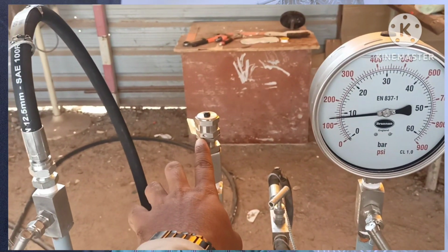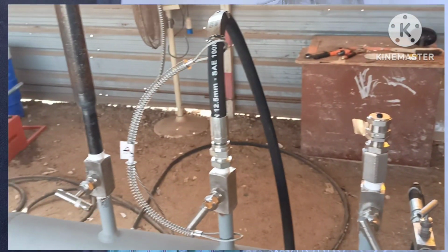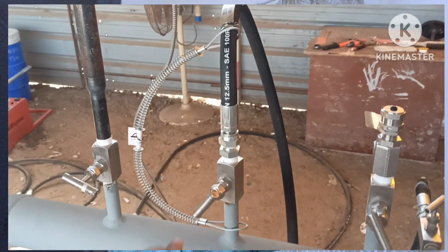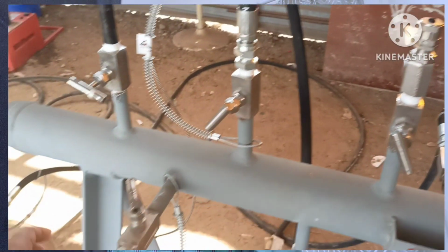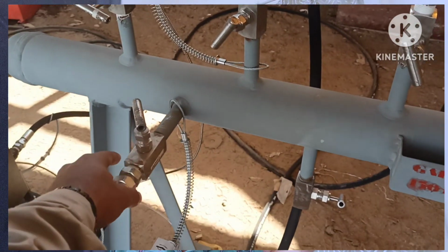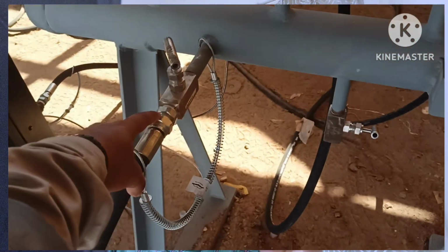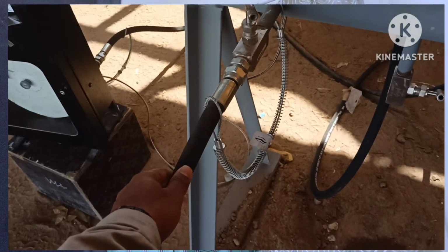Flushing exactly means when the line is pressurized to 4 bar or 3 bar, that time you go to the top of the vent point and open it. That means all the pressure up to 3 bar is released and comes down to 0. That means air is also removed from that area. Flushing also takes 20 or 30 minutes, and then after flushing you close the valve and stop the water filling.